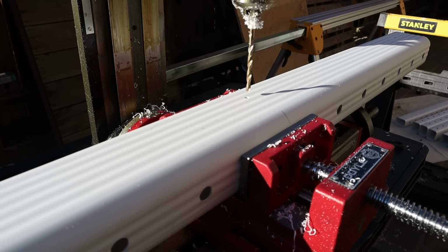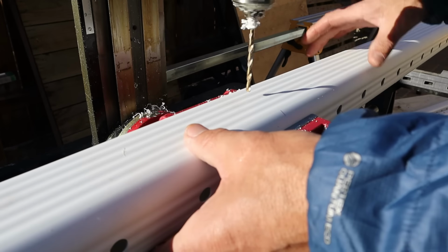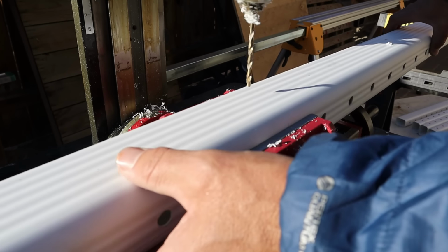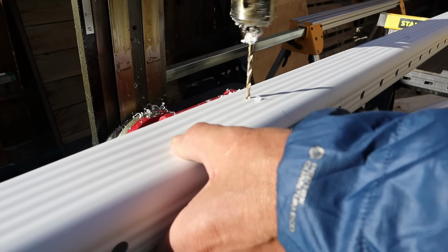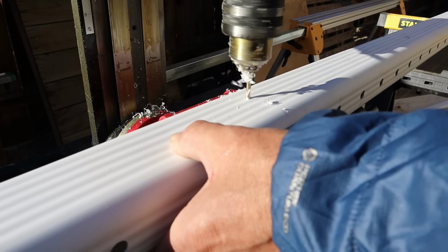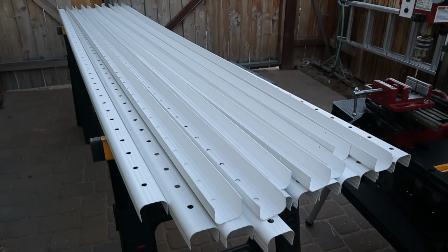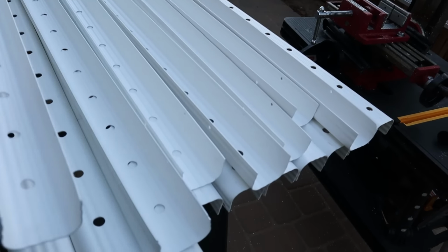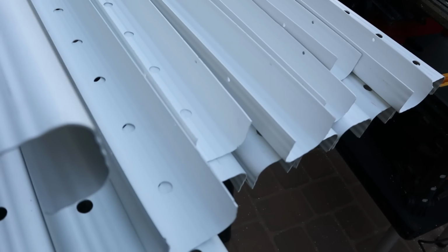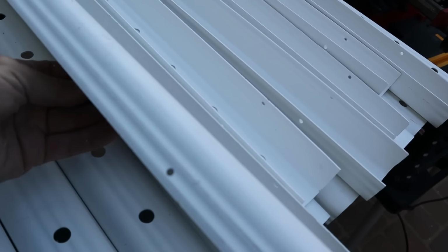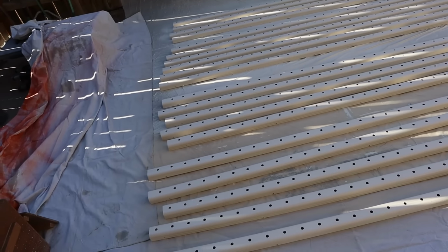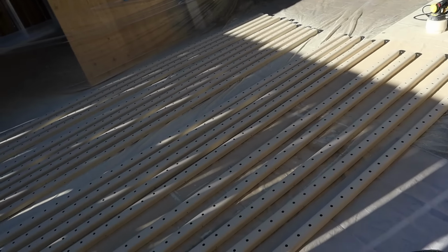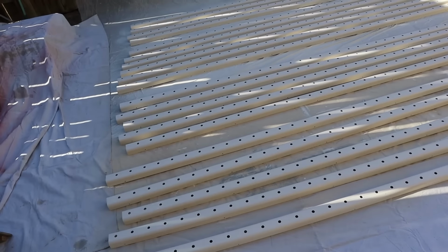And then I put the channels on sideways so I could do my mounting holes, and I just made sure those were big enough for the screw to fit through, and those go all the way through both sides of the channel. Now once I had all of my holes drilled and done, I just ripped all of these in half on a table saw. Table saw is a little bit messy, but it is pretty effective and works. So you end up with all of these half channels. And then I painted them to match the underside of my eaves so that they would blend into the house a lot better.